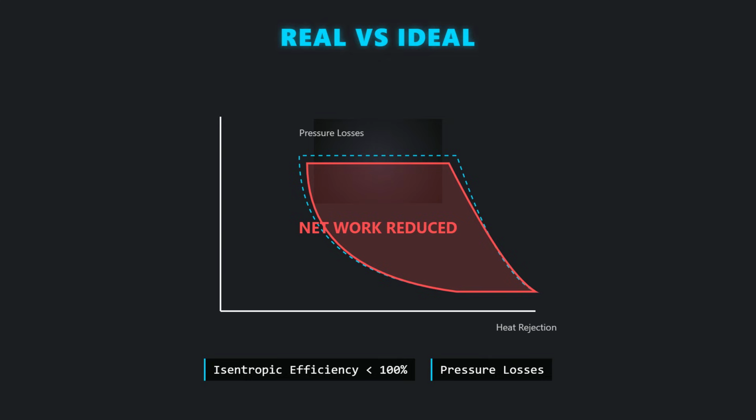Thermal efficiency is maximized by simultaneously increasing the overall pressure ratio and the turbine inlet temperature, T3. Conversely, propulsive efficiency is optimized by minimizing the velocity difference between the exit velocity and the flight velocity of the aircraft.